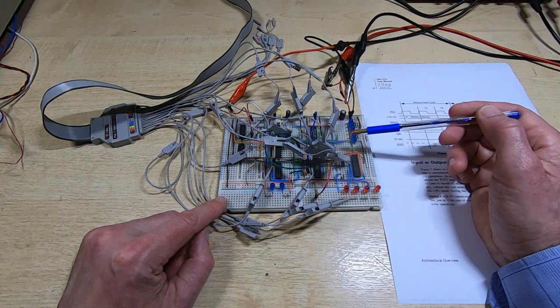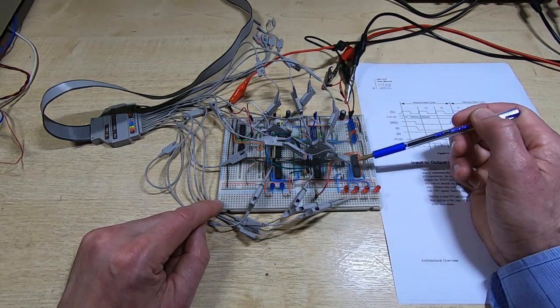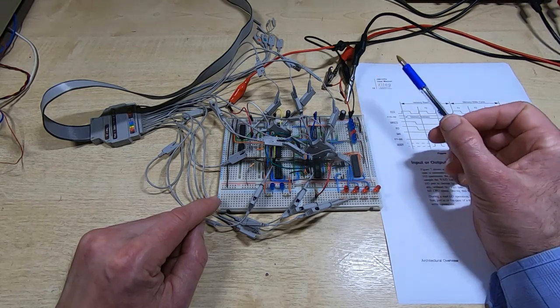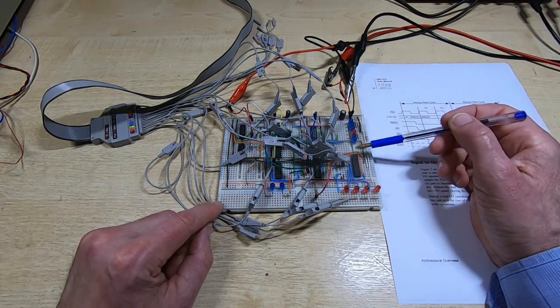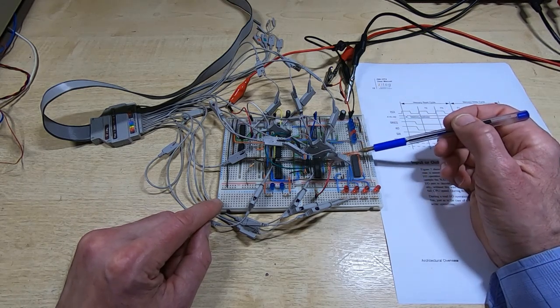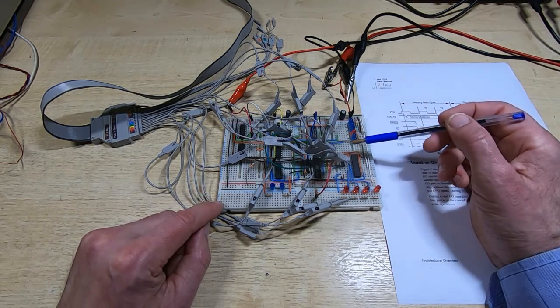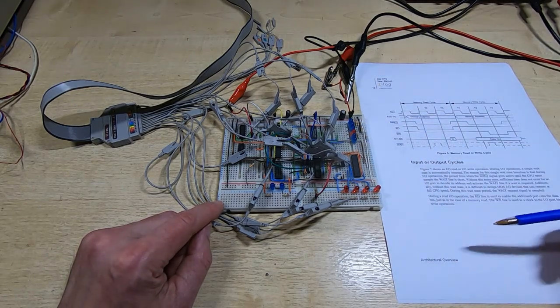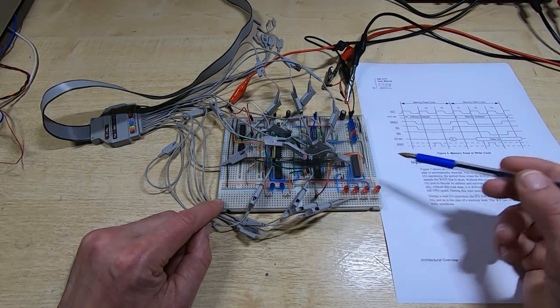This also takes signals from the latch that you saw on the floppy drive interface to control the direction of the transfer, whether we're reading the floppy disk or writing to it. And it also incorporates a gate so that we can disable the DMA transfer and use programmed in-out if we want to continue using it in the way that you've seen it working already.